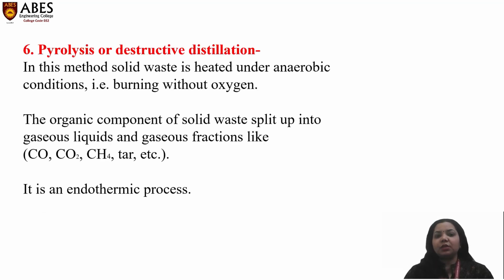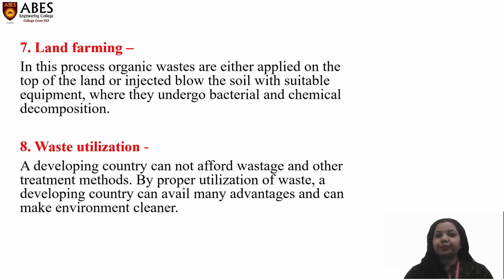Next is pyrolysis or destructive distillation. This method is called destructive distillation as it burns solid waste without oxygen. In this method, the solid waste is heated under anaerobic conditions. The biodegradable organic compounds of solid waste are converted into liquid or gaseous fractions like carbon dioxide, carbon monoxide, methane, etc. It is an endothermic process. That means it requires energy.